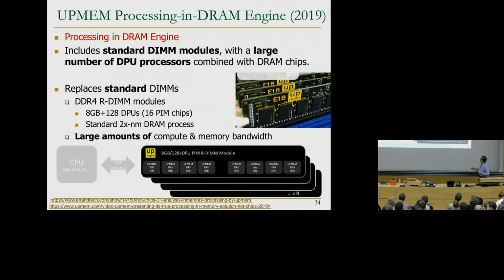It's UPMEM. And it's essentially a DRAM module. It's a memory module, but it has processing inside it. So you could actually process the data where it resides, or close to where it resides. I'm not going to go into the detail of it, but basically, this way you don't need to bring the data into some other processor through energy-hungry, long latency interconnects. You basically bring the data into a processor that's inside the same DRAM chip, and that way you reduce the latency and improve the energy efficiency. You don't cause a lot of data movement across the system. So this is very fascinating, I think. And this is actually another paradigm that is going to be very interesting to follow going into the future.